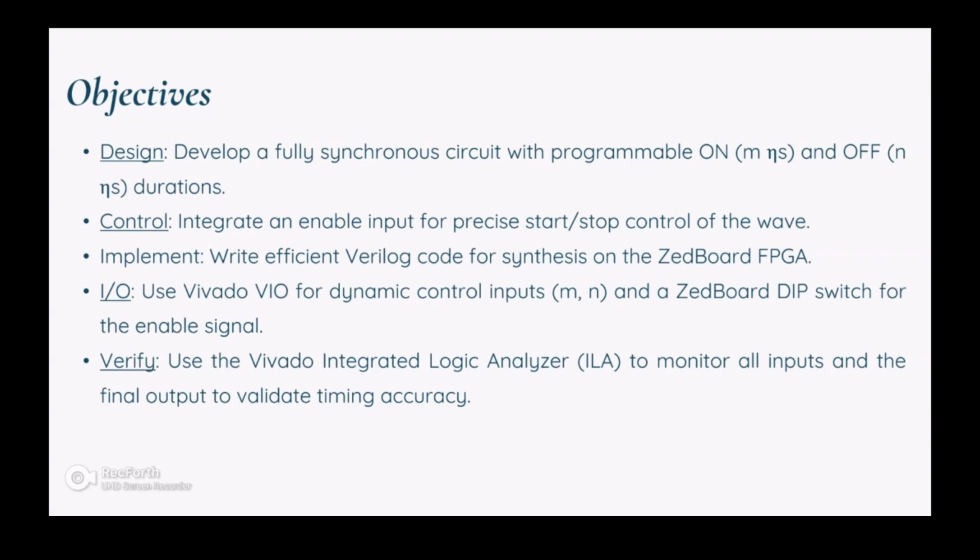Verification. Our most crucial objective is to verify the operation using the Vivado Integrated Logic Analyzer, ILA, tool. We perform real-time on-chip validation by tapping the control inputs and output, and a special 20 nanosecond reference clock. This allows us to accurately validate the generated square wave's duty cycle and frequency against the desired values.